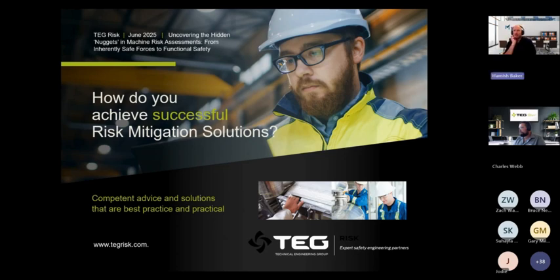A question here from Andrew Walton. When calculating a hazard risk number, so that's HRN, we use degree of possible harm, DPH, frequency of exposure, FE, likelihood of occurrence, equals HRN. In our risk assessment, we don't single out possibility of avoidance as a separate value when calculating the HRN. It's considered and included in the selection of the likelihood of occurrence value. Should we add possibility of avoidance to our risk assessment HRN calc for PLR determination? We need it as a separate component anyway.